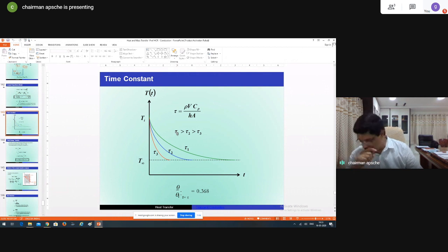You insert a thermocouple into it, and if the thermocouple is not reaching the ambient temperature... The thermocouple principle is the Seebeck effect. When two dissimilar metals form two junctions, an EMF is induced in the circuit. The EMF can be calibrated to record the temperature. That is the principle by which it works.